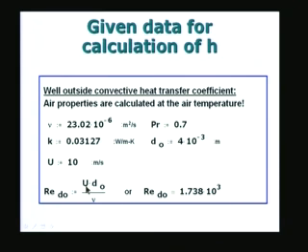It is defined as the velocity u multiplied by the diameter of the tube. When I say the tube, it is the well I am talking about, the outside diameter of the tube which makes up the well, and the viscosity of the fluid which is moving. This is the kinematic viscosity nu, and from the tables of air properties we take these values at a temperature.